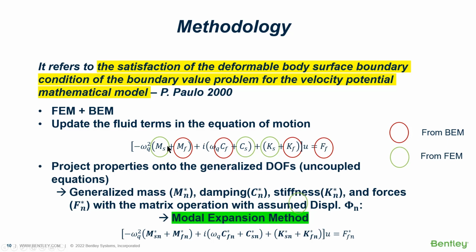Also, here, the structural mass of the structural element, and the structural damping, usually input directly to the software, and then the stiffness of the structural element are also plugged into the same equation. Then, using the orthogonality of mode, we get uncoupled equations with generalized mass, damping, stiffness, and also forces.